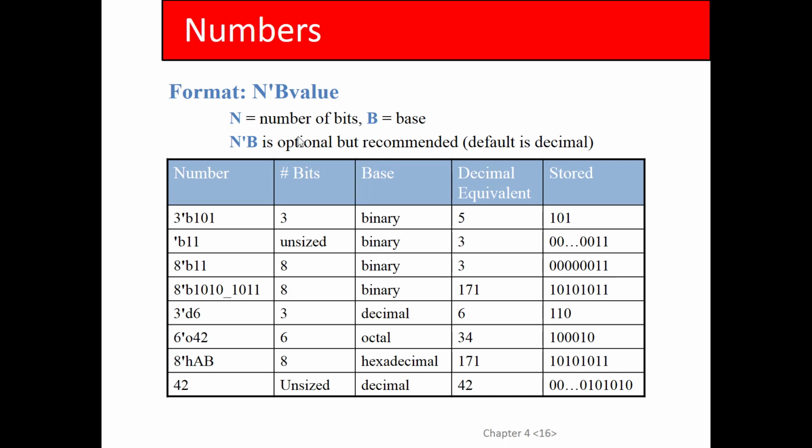So my advice to you is when you write in Verilog, try to not write code that generates any warnings, because otherwise you'll end up with tons and tons of warnings, and you may get a warning in there that's actually important, and you may miss it because there's an avalanche of warnings from just writing code that's careless, where you don't specify the sizes. You guys with me?